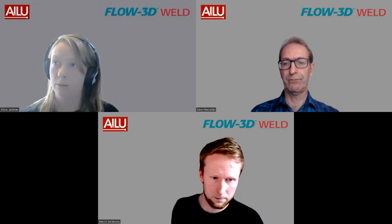And there's a lot of correlations that need to be drawn between what you know from your experiment back to the simulation, to use the simulation to find the optimal parameters. So there's a study, which I didn't talk about today, from GM that found there's a certain concentration of copper when doing a lap weld that would increase the propensity of cracks to form at the surface of the material. And so they were using the simulation to reduce the amount of mixing below that threshold that they found more or less experimentally.